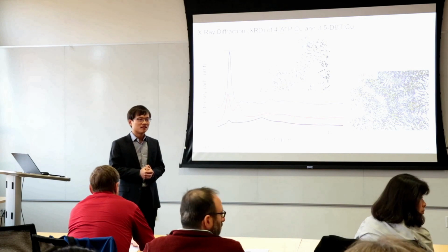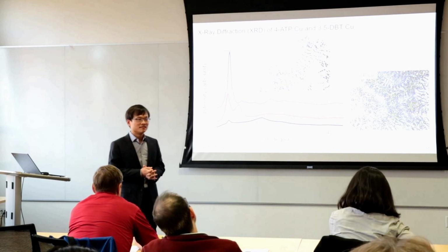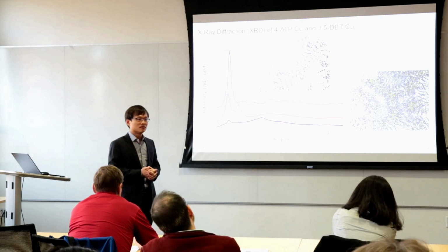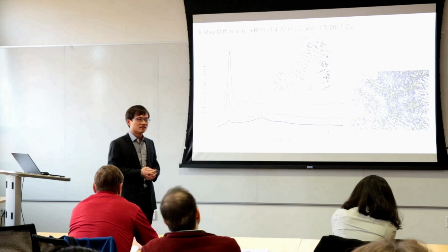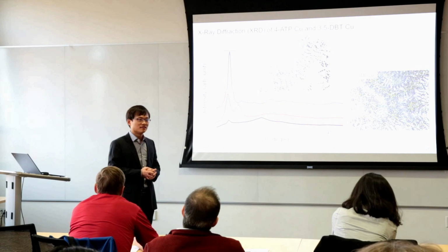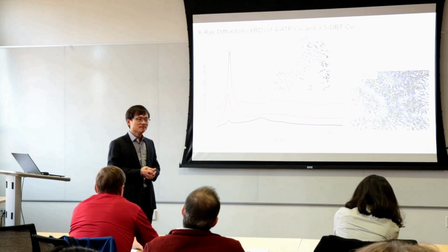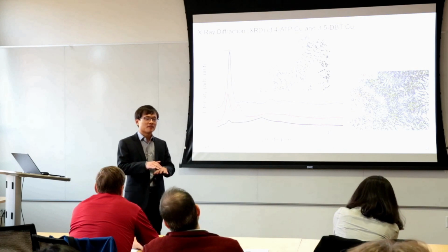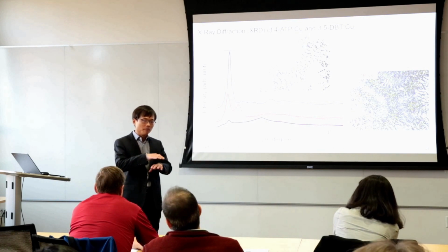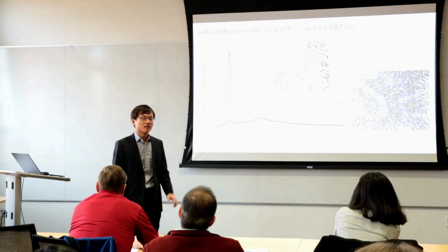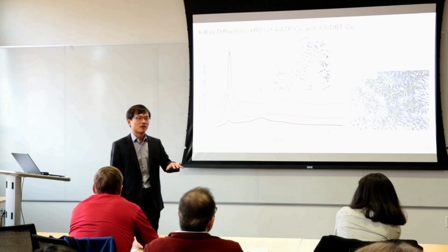With the hybrid layers containing organothiol, do you think that, well, one, is electromigration an issue outside of the interface? And do you expect it to just mitigate electromigration that occurs at the interface as opposed to inside the bulk of the copper? Yeah, for this hybrid layer strategy that we developed, we are aiming to mitigate the surface copper atom migration. The hybrid film doesn't go into the copper itself. Right, so that's the surface copper migration that we are trying to minimize.